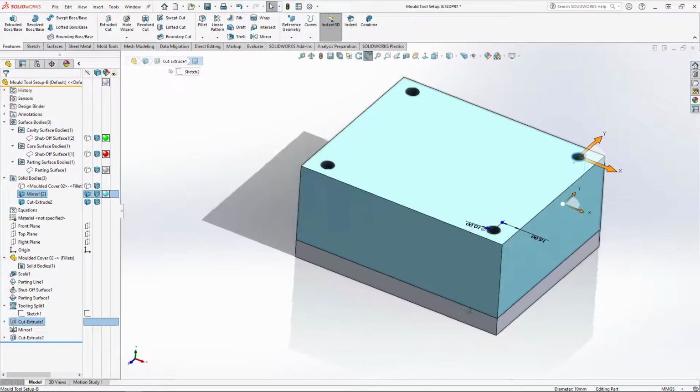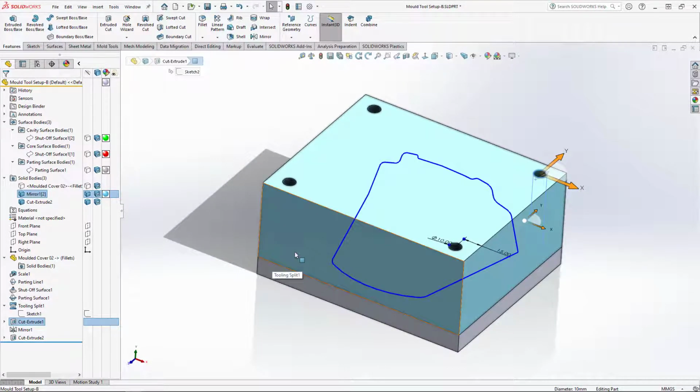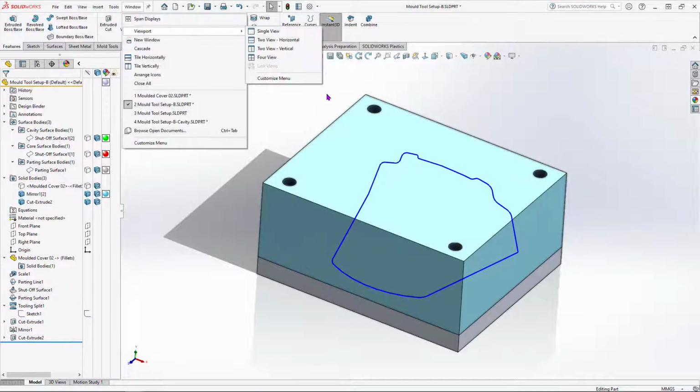So I'd encourage you to read about mold design, what sort of features you need to include in a mold design, such as clamping holes, cooling channels, injection locations, all these sorts of common features. But you can add them into this setup just by ensuring you have enough material and then creating the required features. If you need to cut material away, you can use extruded cuts, very easy to set up. Yeah, and you can add those features in, and then when you add them, they end up being shown